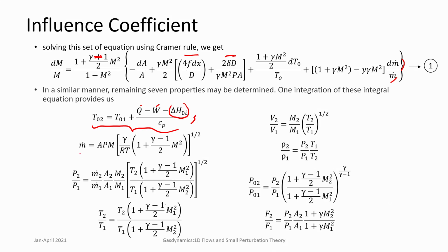So, mass flow rate is nothing but rho A V. If you consider two particular points, or a particular point, you can relate it to pressure and Mach number. This was done in previous classes. From here we can get to P2 by P1, and since there is an injection of mass also, m2 and m1 need not be the same, that should be understood over here. So, if you can solve for, say, Mach number, you have to integrate. This can be integrated using any numerical tool, there is no analytical way this can be done.